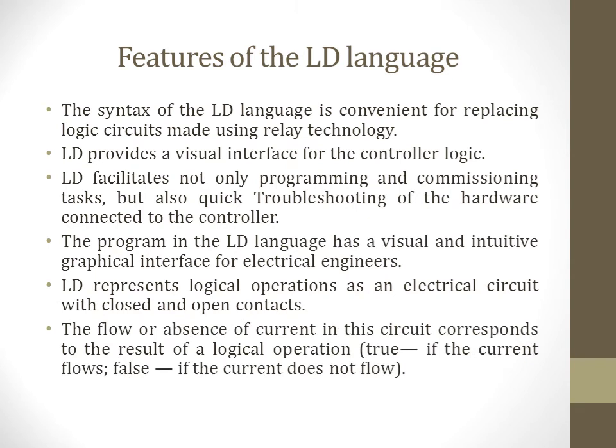LD represents logical operations as in electrical circuits with closed and open contacts. The flow or absence of current in this circuit corresponds to the result of a logical operation. If we have the current, it means that we have true as result in our circuit.